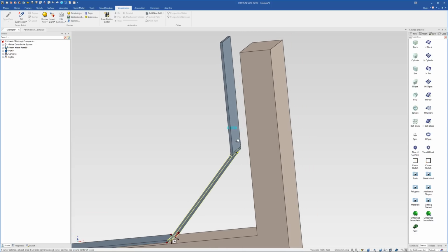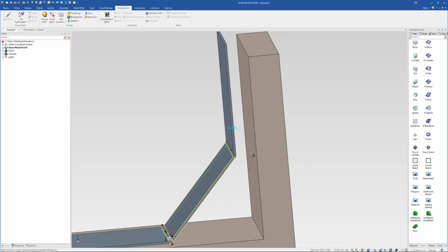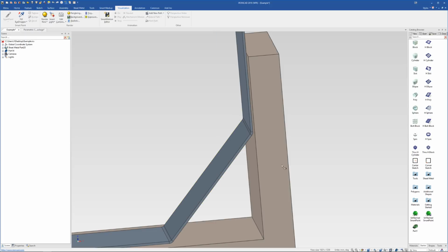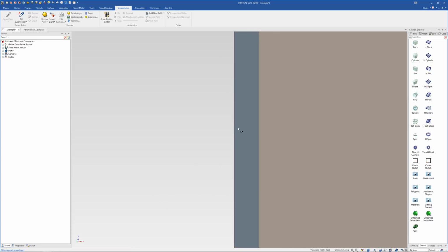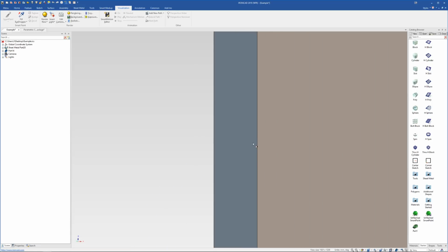You can see that handle down there has now moved so that it's facing this way. When we drag it, it's going to use that top point as its reference point. You see when I hover over it, it's showing what the reference point is. Now if we hold down the shift key and drag this and snap to that wall, it's going to snap exactly into place, and it will be a perfect fit going up against the wall. Let me use the look at tool so we can get right on that.